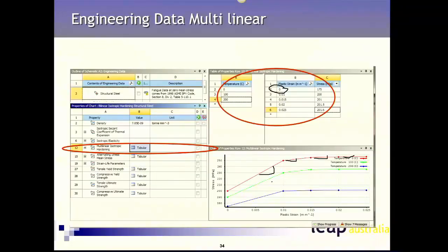Okay, so generally it's a good idea to have data that will cover your expected strain and stress range, but where you've got local singularities, you're not going to account for that. So you just have the data in the expected range.